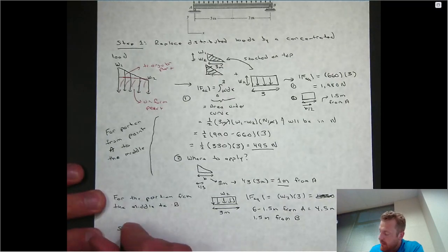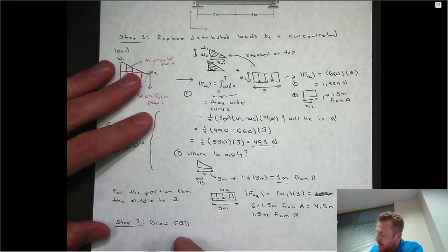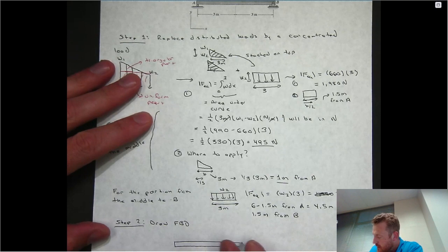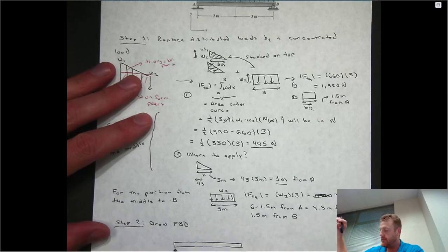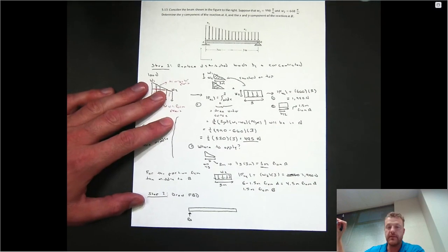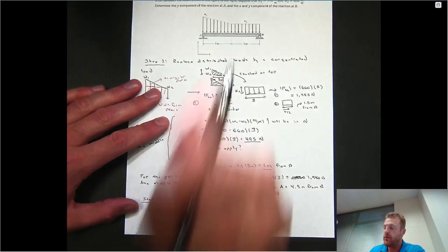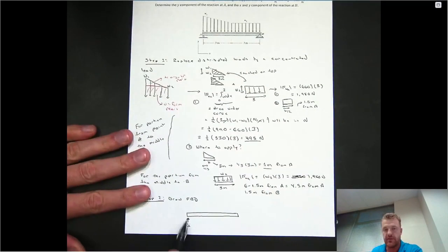So now that we have that, we can actually draw a free body diagram. And the way that we will do that is we will just separate our beam from its supports. As we were told in the problem description and as we argued earlier, the reaction at A can be replaced by a single vertical reaction. And what that is saying is that for this loading, the horizontal component of this force is 0. But if we were to remove it from that roller support, we need to account for what the roller support does to the beam, and that actually pushes it up.